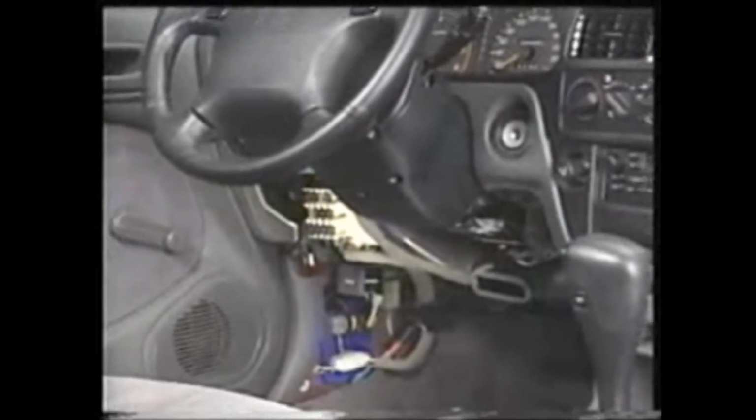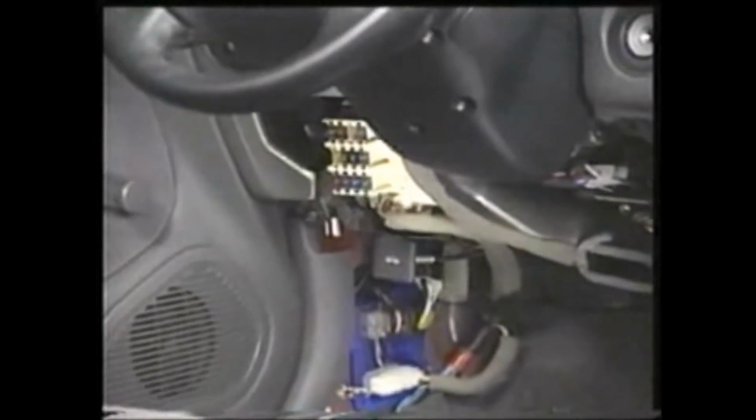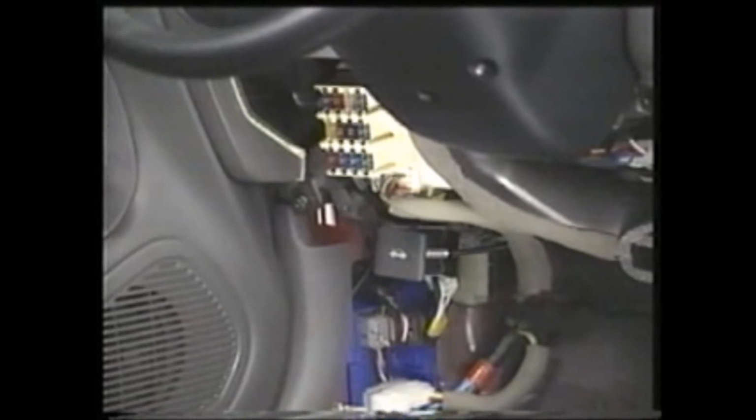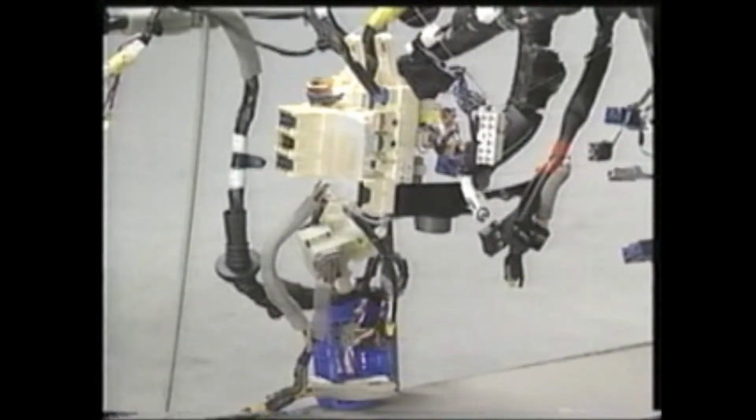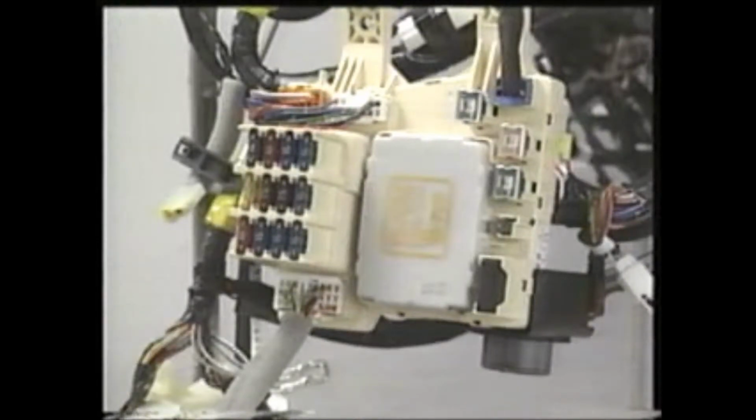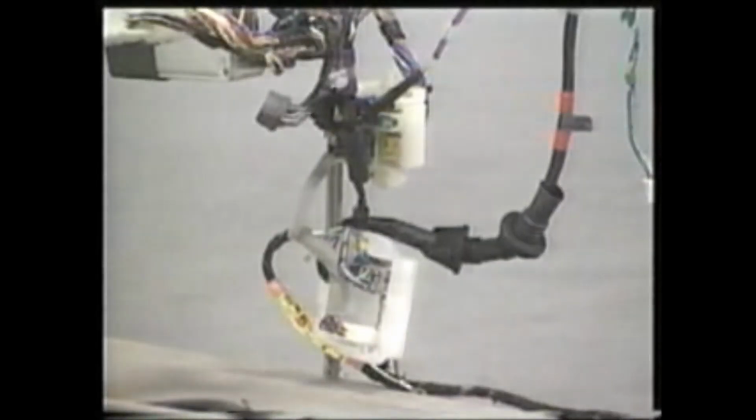Now we look at the kick panel on the driver's side. Here, the cowl wire harness, instrument panel wire harness, floor wire harness number 1, and front door wire harness are connected by junction block number 1, or with each other via harness-to-harness connectors in the vicinity of junction block number 1. In junction block number 1, the fuses and relays are installed in the same way as with junction block number 2. As is true for the cowl side on the passenger side, the individual wire harnesses are joined by connectors.